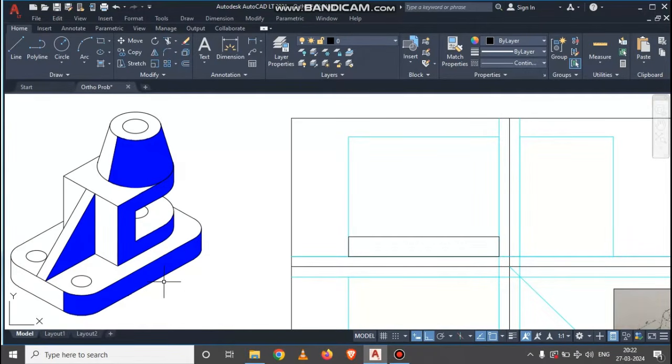Now the next point is we have to represent this portion, and we have 55 mm from this corner point till this point. So we can draw a line from this corner with length equal to 55 mm, and from that we take height equal to 60 mm. So let's start with this projection. Again select the line command. You can select this corner point, which will represent this corner point. This corner point and this corner point are in line with each other.